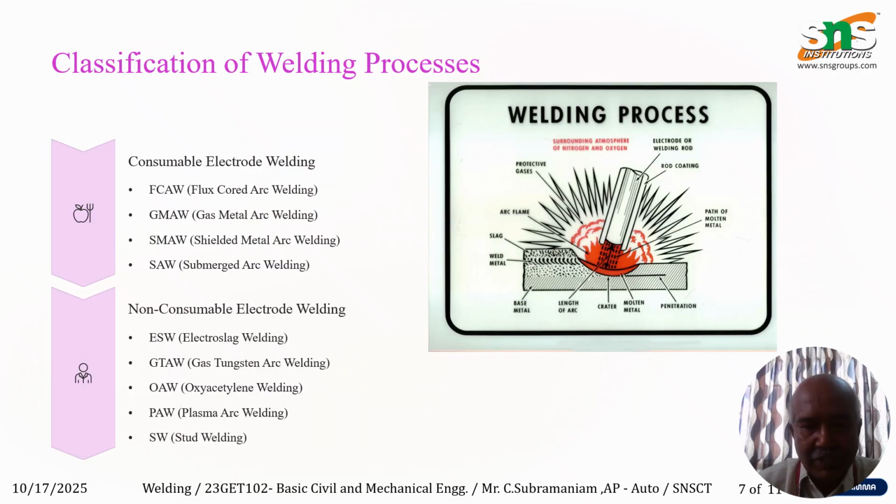And next is the welding process. What is the welding process? There are two processes: consumable electrode welding and non-consumable electrode welding. Here is the welding method. This is the distance between the electrode and the parent material, which must be 3 to 5 mm, such that the electric current may pass, and the weld metal can be melted from the electrode as well as the parent material. And this is the parent material here, and this is the depth of the welding penetration itself.